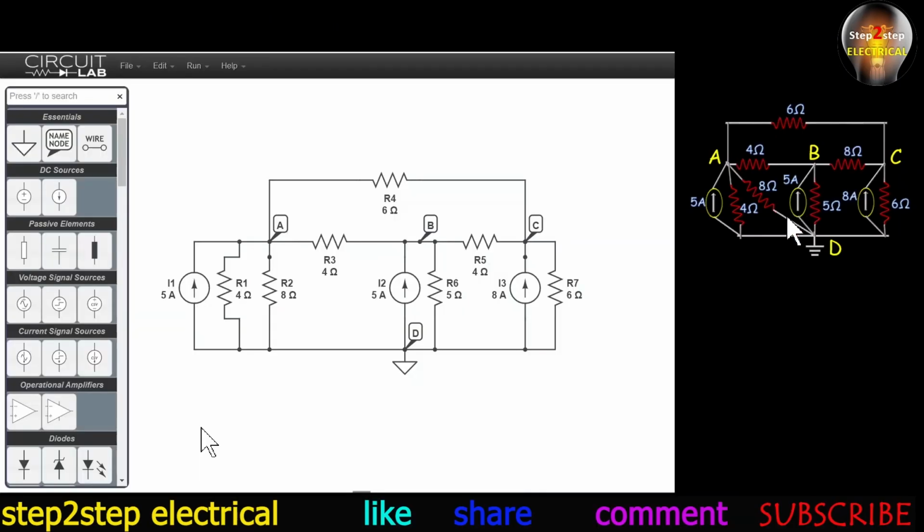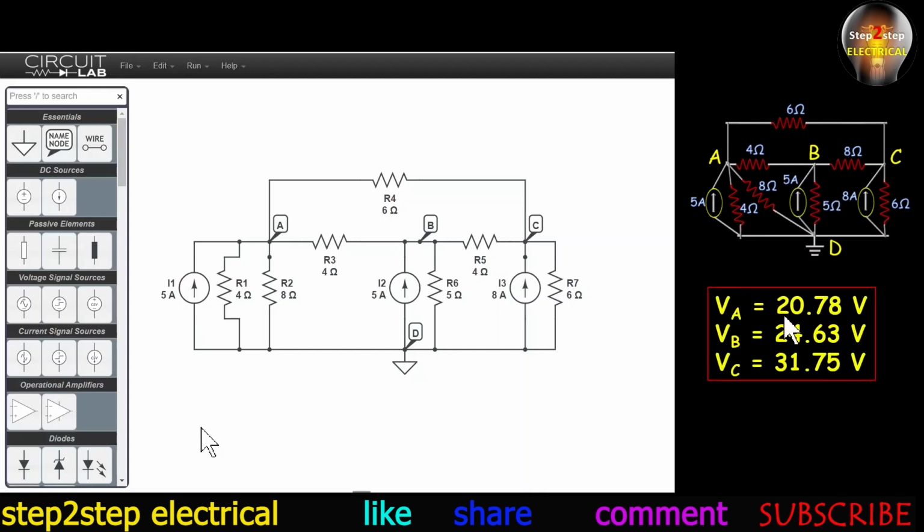So now you can see that this is the circuit which we have solved and obtained this result. Now we have to verify whether this result is the same or not. And you can see this is the same circuit here. So let's check. You can see in the result VA is 20.78, but here in the lab it is 20.81 volt. In the result VB is 24.63 and here it is 25.5 volt in CircuitLab. So again here it is approximate. In the result it is 30.75, here in the lab it is 30.59 volt.